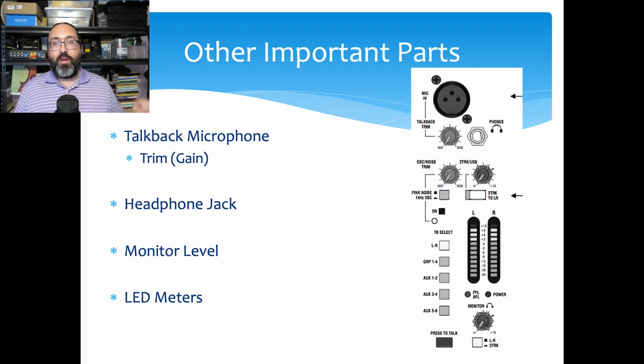Unhit the PFL meter, hit our left right select if we want it to go to left and right, slowly bring up the channel fader as we are talking into it, and hopefully that channel should be working out of that speaker if everything else is connected correctly. This is how we meter whether those channels are working or not.